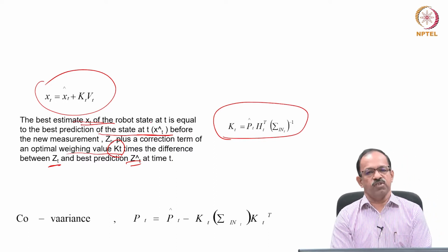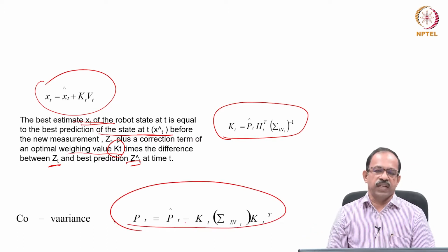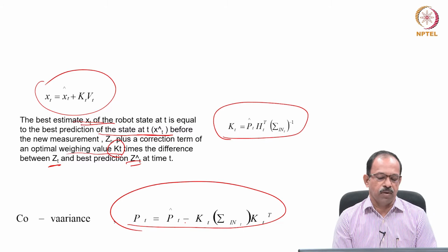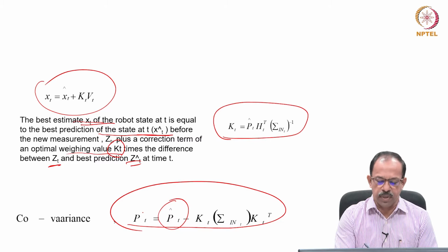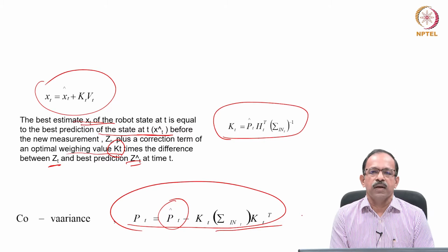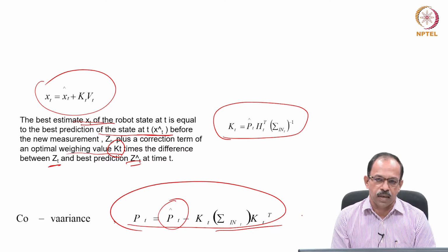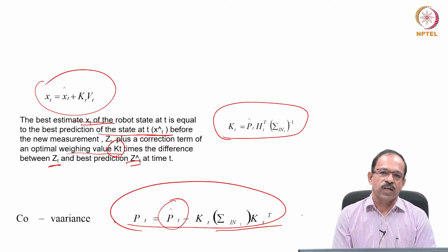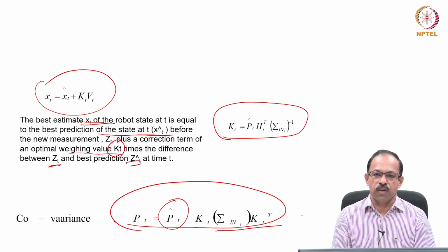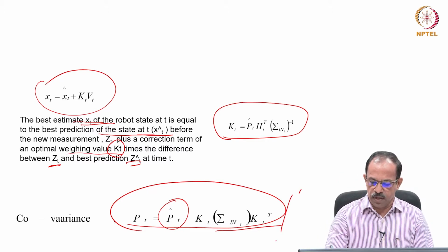be the new position estimate of the robot, and the covariance is this one, Pt, because then again this Pt will be the covariance at that estimated new position, and you can see it will be smaller than P̂t, because these are all positive. So, it will always be smaller than the previous covariance, that is, the predicted covariance or the movement covariance due to the motion of the robot will be reduced to a new smaller value when we have a perception update. So, that is how we get the new estimated position.